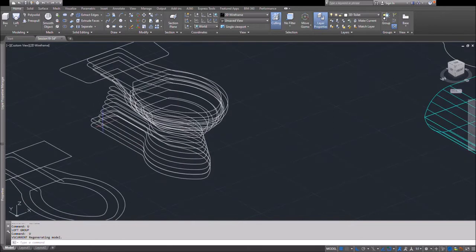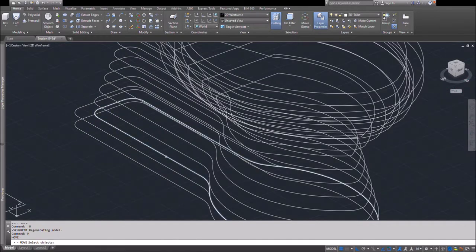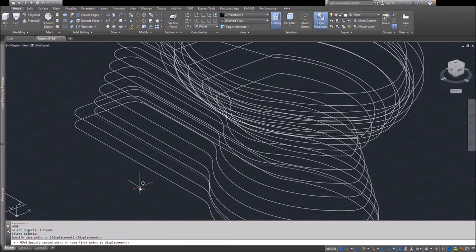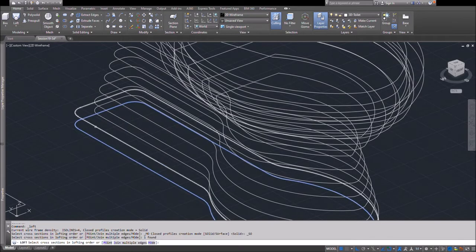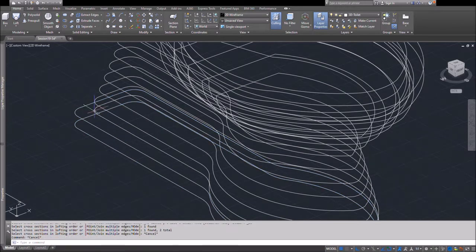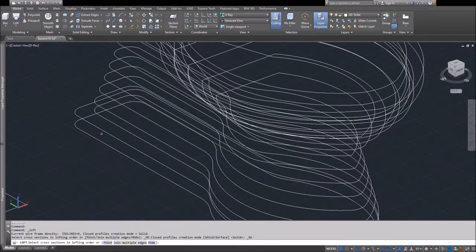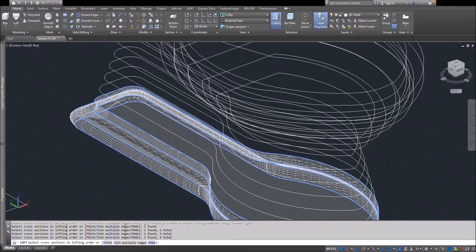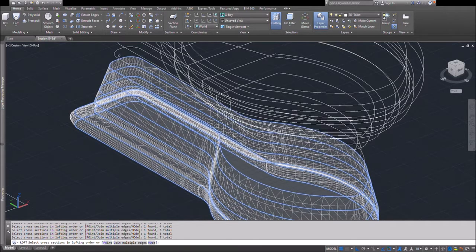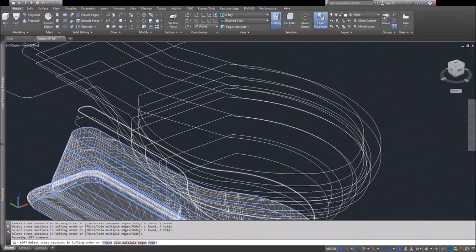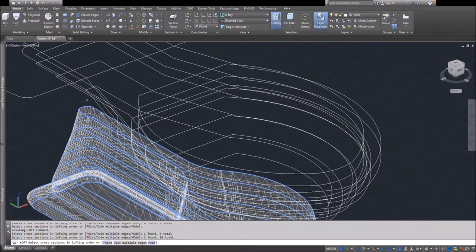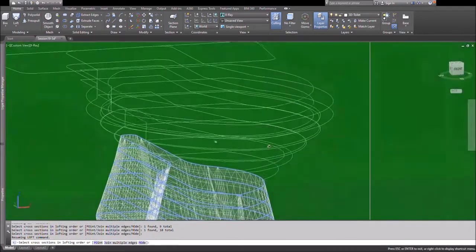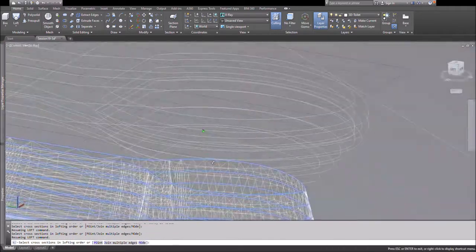And it happens. So here I'm just looking at these polylines, and I'm tweaking them a little bit. I'm starting to loft it, right? The command is loft. It's under the extrude button, and I'm starting to loft these polylines to create that surface, right? I'm taking the first two and then the third one, and as I start to pick all the other subsequent vertical profiles, you can see very easily and quickly that it's generating the surface of this object,